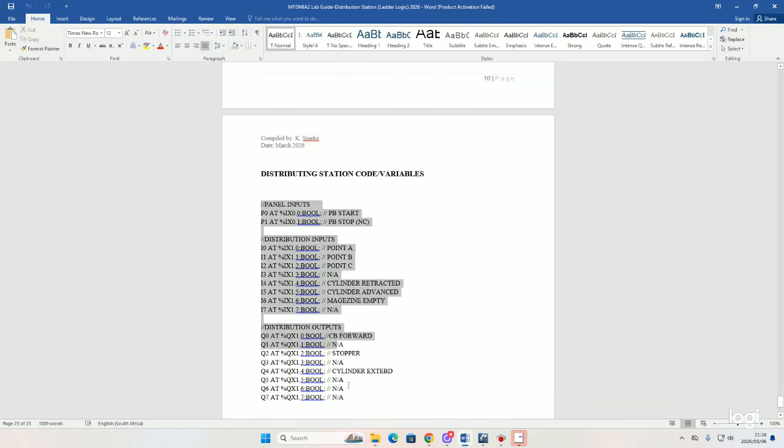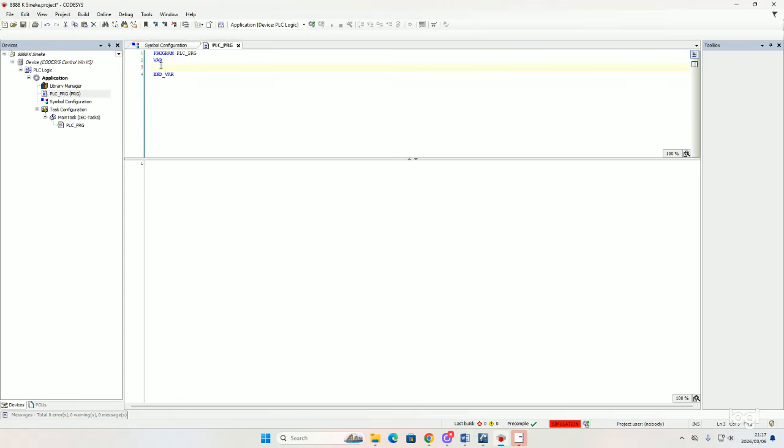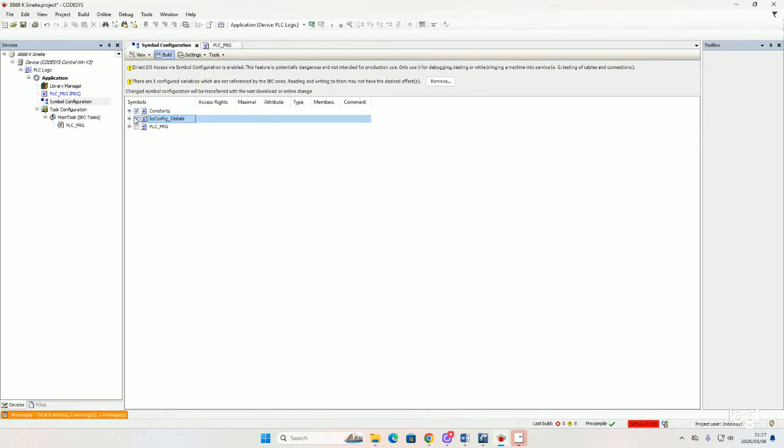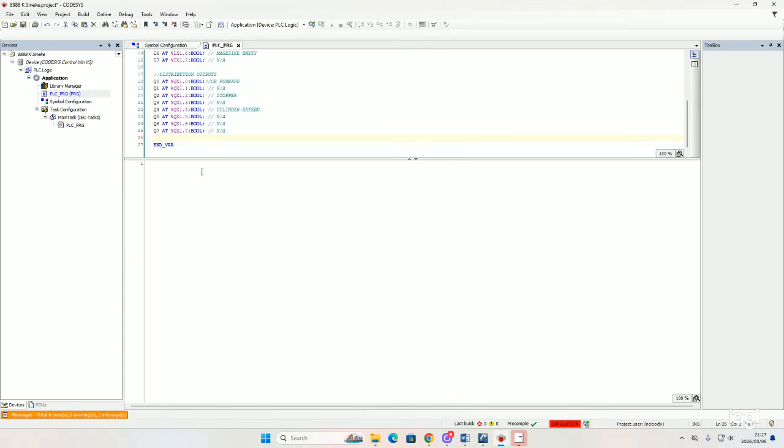Go to your code, you copy, and then paste it between your VAR, which is variables, and END_VAR. From there, that's when we can build. So it's perfectly okay if you're going to start building and enable only these 2 options. Thereafter, inserting your code, you come back and enable your code as well. There's also absolutely nothing wrong with that.